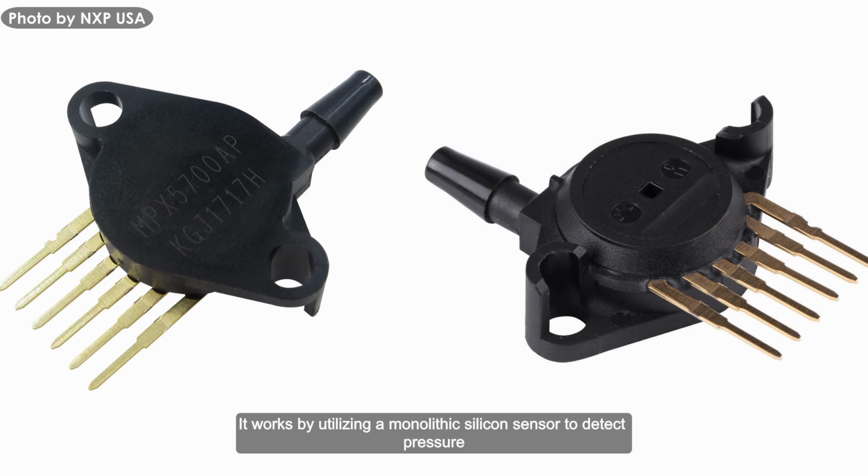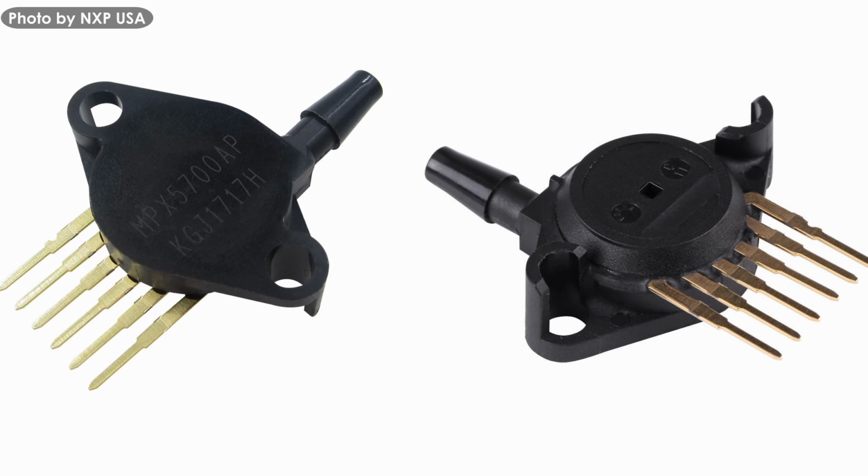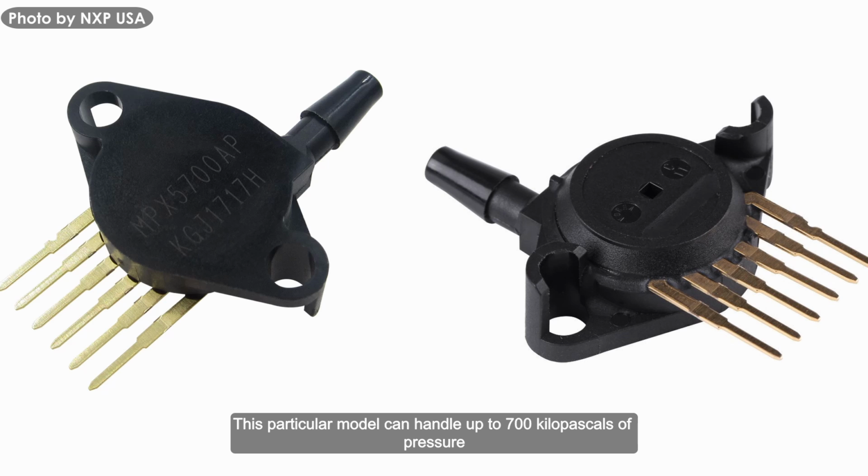It works by utilizing a monolithic silicon sensor to detect pressure and a single element transducer to convert that value into an analog signal for a DAC to process. This particular model can handle up to 700 kilopascals of pressure.